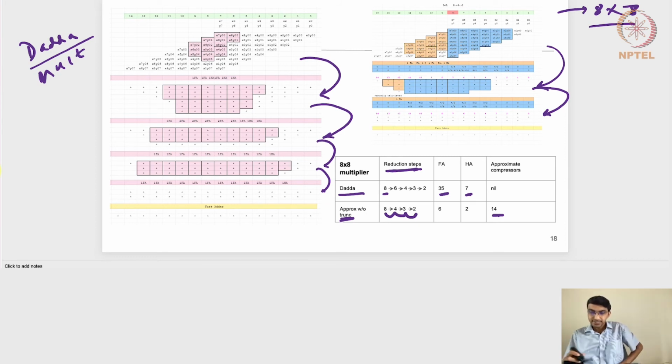So in the partial products stages, or the representation of the partial products and its reduction stages, 1-step full represents that we are applying the approximate compressors only on the first stage, right? Only on the first step, and from the second step onwards there are no approximate compressors at all.